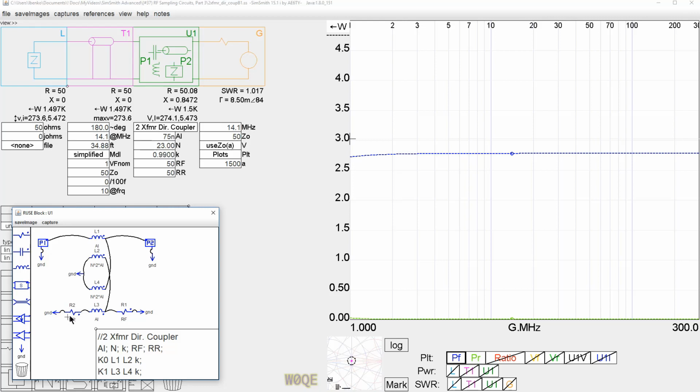And these resistors right here are really outside of the unit. They're in the equipment under test. And if you aren't using the reflected power, you'd either put an internal 50 ohm load to ground on it, or you'd put an external terminator on the coax connector.